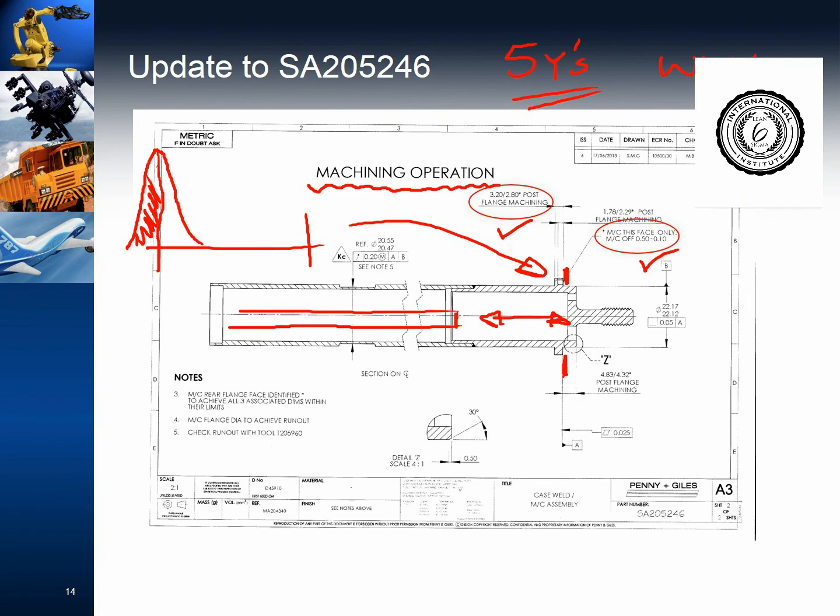Why was the tolerance changed, etc. If you want to do the 5 whys analysis to get to the real root cause, why did we not know that that face had another customer associated with it other than just the final customer? That would be a great thing to do. It's not something that they've done in this case study. They found the problem, they fixed the jig, they've centered that distribution.